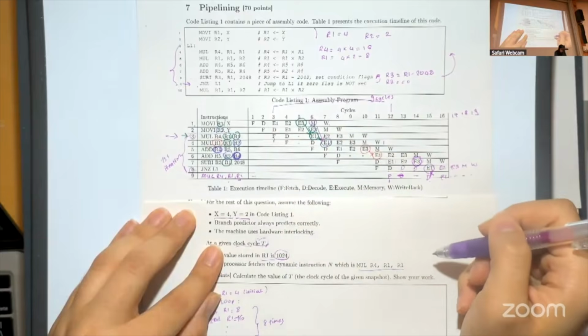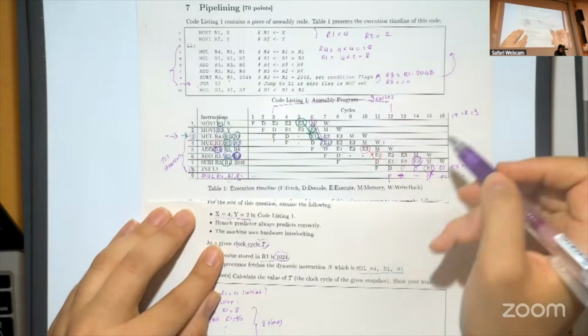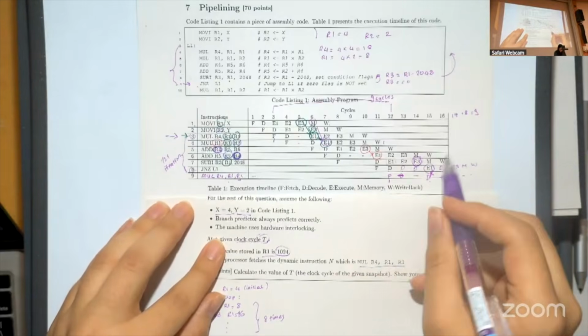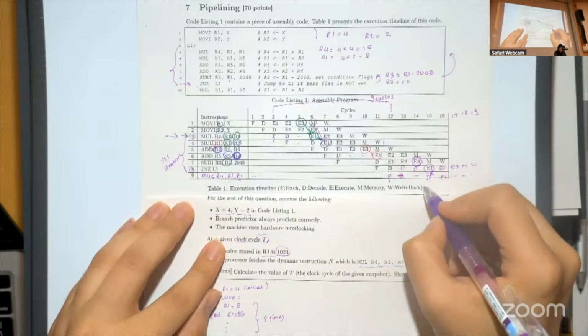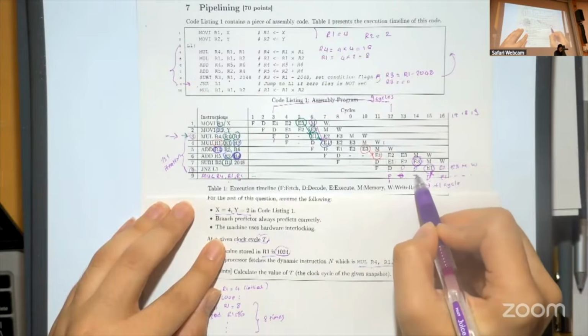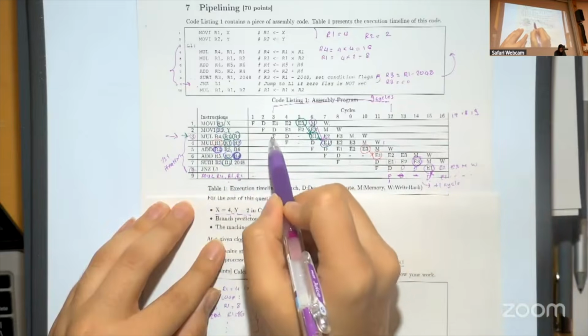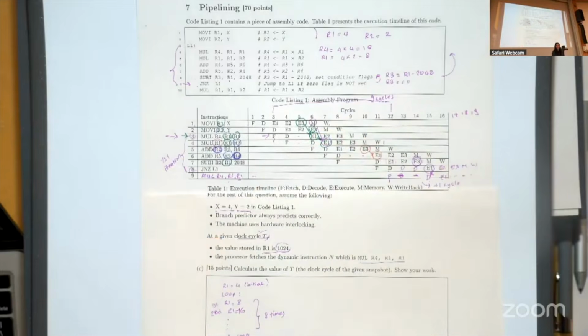And here is a little trick, basically. That's different than the next iterations because we will have an extra 1 cycle here that is coming from this stall, because this is different than the first fetch that is here. So maybe this part was a bit confusing. Do you want me to explain it again?